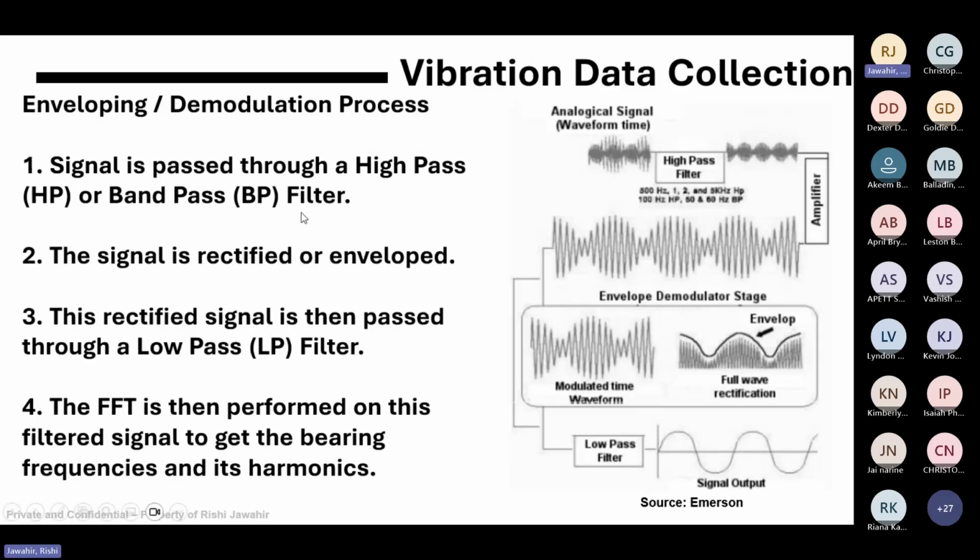Right, so basically explaining what is envelope demodulation. This is the principle of most of the vibration equipment out there to diagnose bearing defects, especially those high frequency range types of defects. So how I like to put the analogy, most of us here in Trinidad are familiar with cricket, all right? Or any kind of sporting event, you may go to a stadium where there's a lot of noise actually happening there. But in the middle of all that noise, trying to hear a very small ping will be very difficult for you, right?